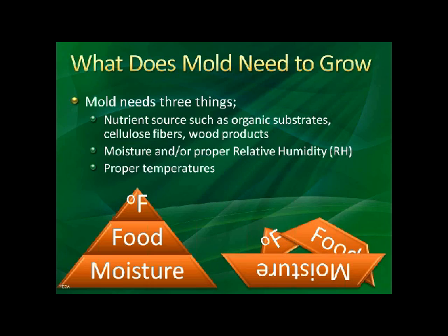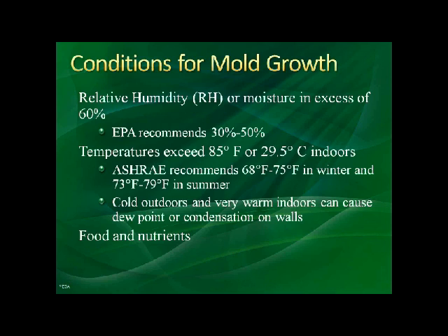The conditions for mold growth, again, are quite simple. Mold really likes relative humidity over 60%. And as I had stated earlier, the EPA does recommend 30 to 50%.